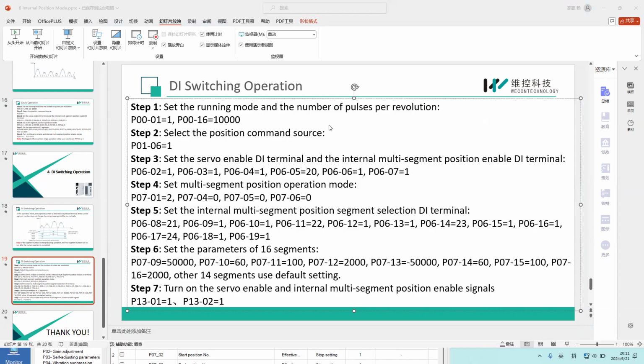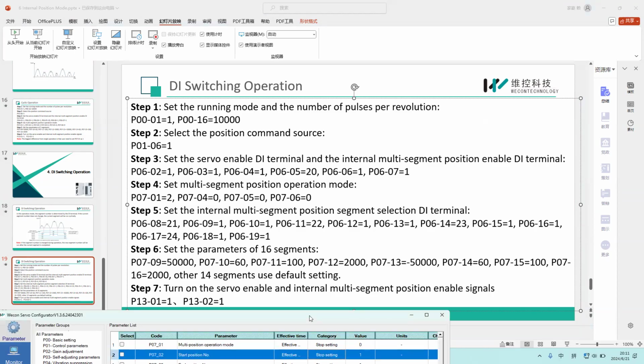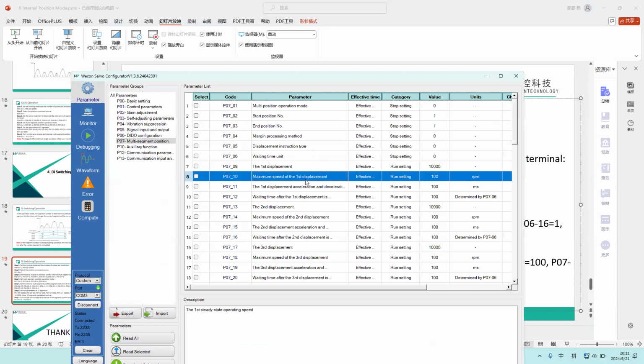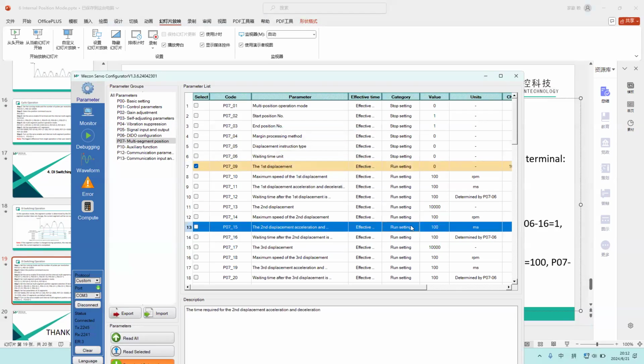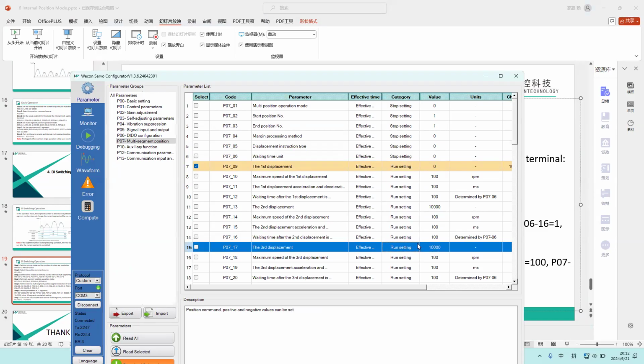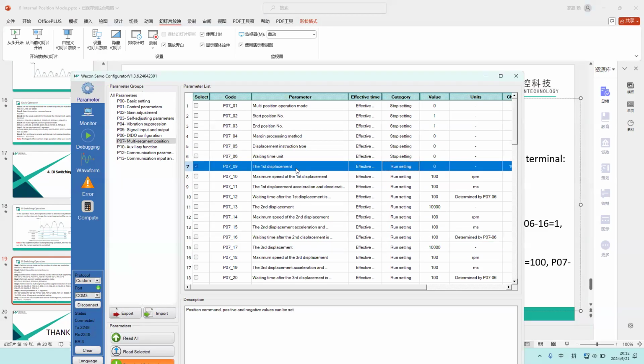This is the first way to stop. And the second way, you can set one segment, for example, segment 1, and set the distance at 0. So for example, you are running segment 2, segment 3, and for now you want to stop. Then you can switch to segment 1, and the motor will stop, because for segment 1 our target moving distance is 0.